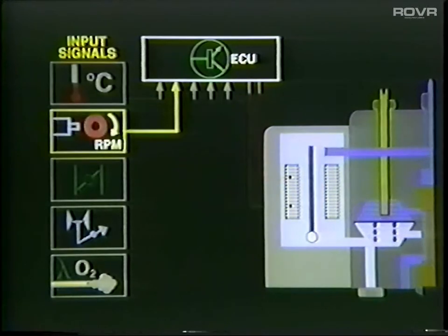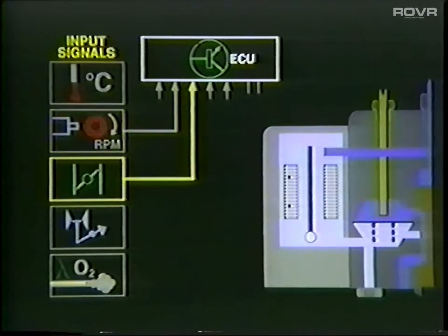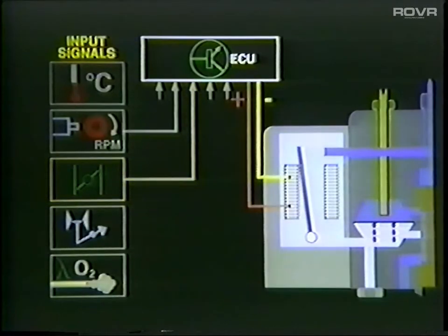The next example illustrates the conditions necessary to initiate fuel shutoff when decelerating. The first requirement is that the RPM signal transmitted by way of the TD terminal of the ignition system indicates a speed above 2,500 RPM. The second requirement is that the micro switch is providing a closed throttle signal. When these two conditions are met, the ECU transmits a strong current flow in the opposite direction.